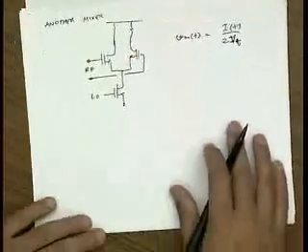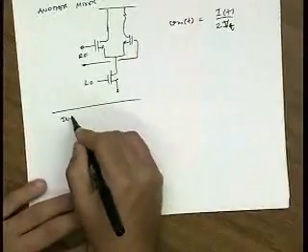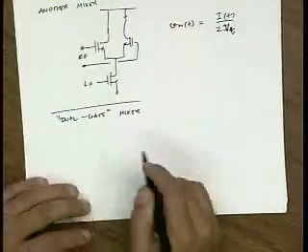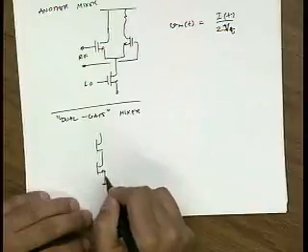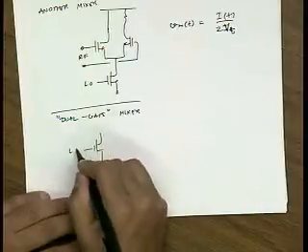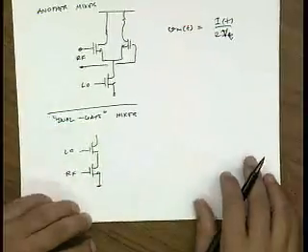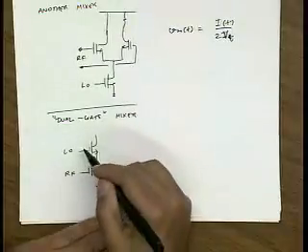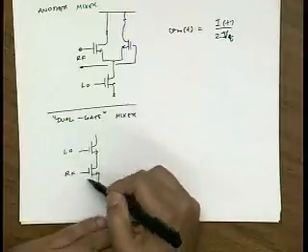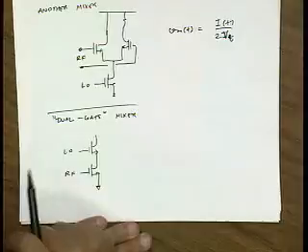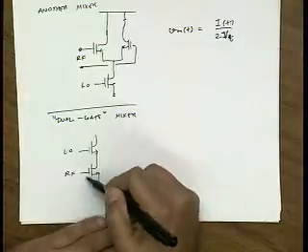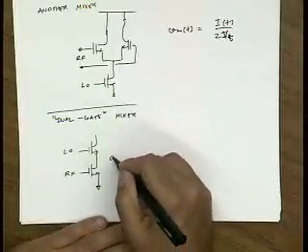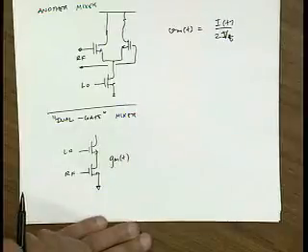Well, last lecture we also talked about a dual gate mixer. And I think it's instructive to review why we can't switch the ports in a dual gate mixer, because this also came up in office hours today. So the mixer we talked about last lecture was we have an LO here and an RF signal here. As far as the RF signal goes, when the LO is not basically negative, when this device is in saturation, this is a regular cascode amplifier. But when the LO becomes sufficiently negative as to move this device into triode region, its GM drops and it creates a time varying GM. So this is also of the class GMT.